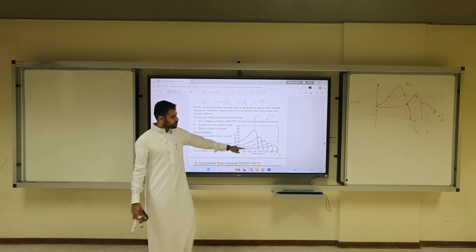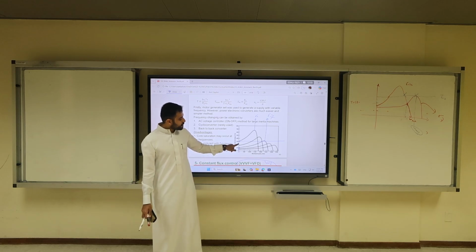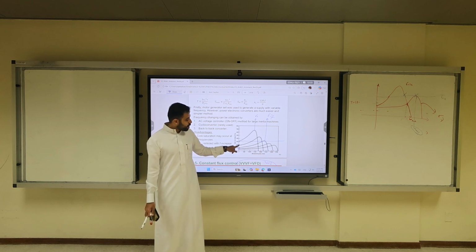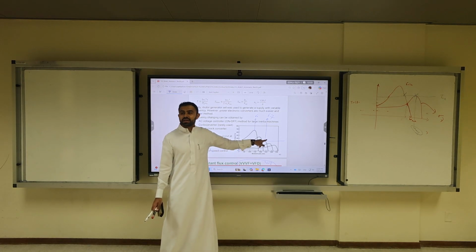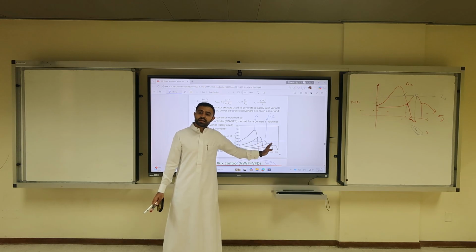while not being in the stable region? It is, anything above that will not be stable. So what's the benefit of operating at 67? You get higher speed, but also you get lower starting current and lower torque. Keep in mind what is happening if you run at 60 Hertz. The load would start to spin. But if the starting torque is less, you have to wait until you exceed the maximum torque and then it will start spinning. In 67 Hertz, the load will not spin until you exceed a certain speed.